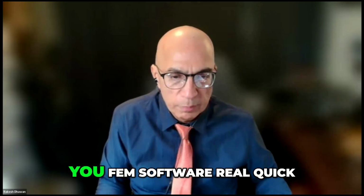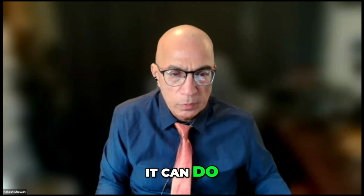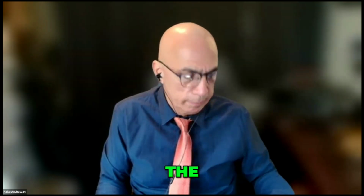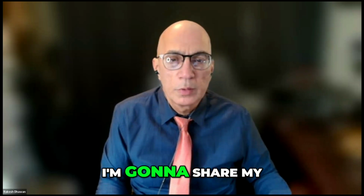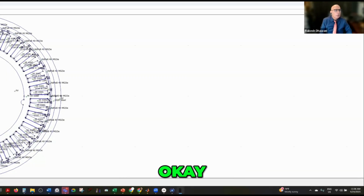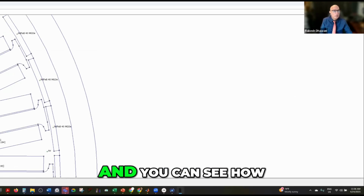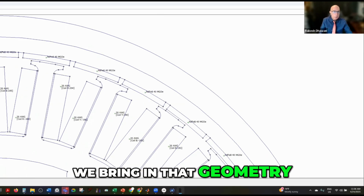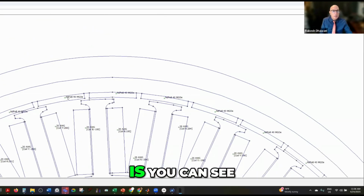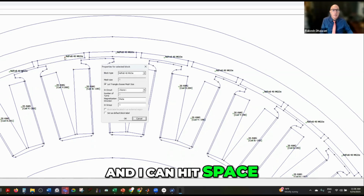So let me show you FEMM software real quick so you can have an idea of what it can do. So I'm going to share my entire screen. So this is the FEMM software here, and I can open this design here. You can zoom in with page up, and you can see how you bring in a geometry. And here what we have done is we have to align. So I select this here, and I can select this point here, and I can hit space,